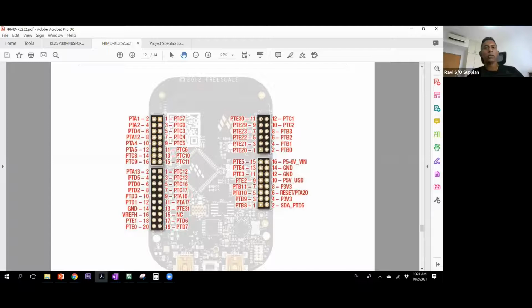You will also need to make some decisions later on how you want to fulfill all the requirements of the project with the pins that you have. There are quite a few different requirements which require GPIO, PWM, UART, and so on. Many of them are multiplexed with each other, so you need to make a decision on what you want to use. There's no right or wrong answer. As long as you know what you want to use and you write the correct code for that, then everything should be fine.